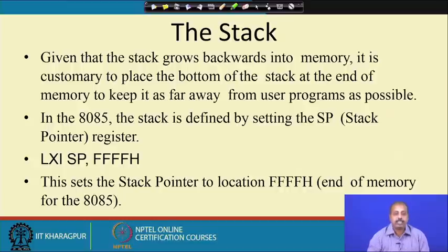In 8085 we know that the total address range is 0000 to FFFF hex. Now, assume we have the entire memory space occupied by physical memory chips. That is, it is not that the actual memory system has less than 64K. We assume that the memory system integrated with the processor has the full 64K space available, so all the places are valid and there is no gap in the address space.